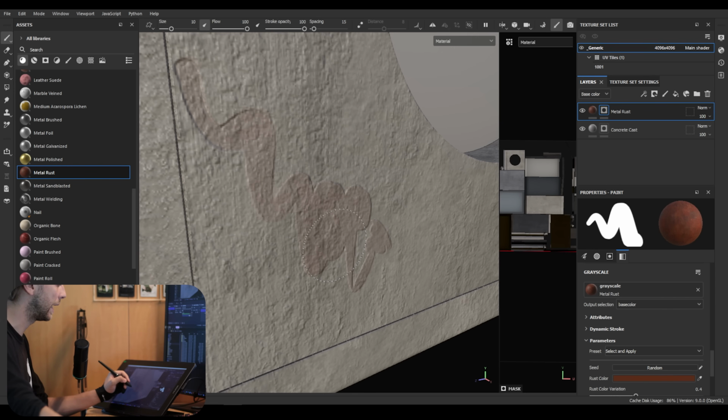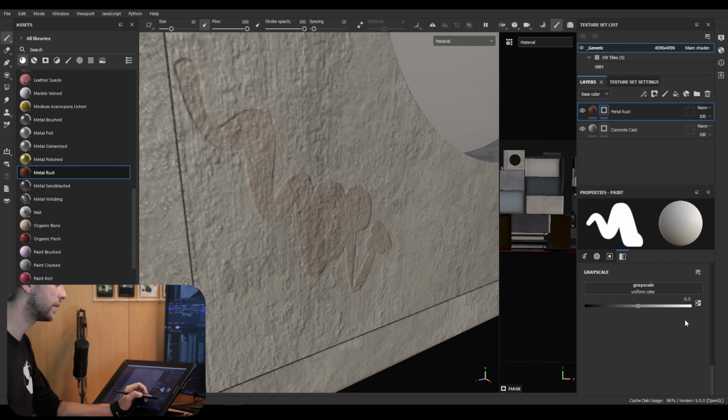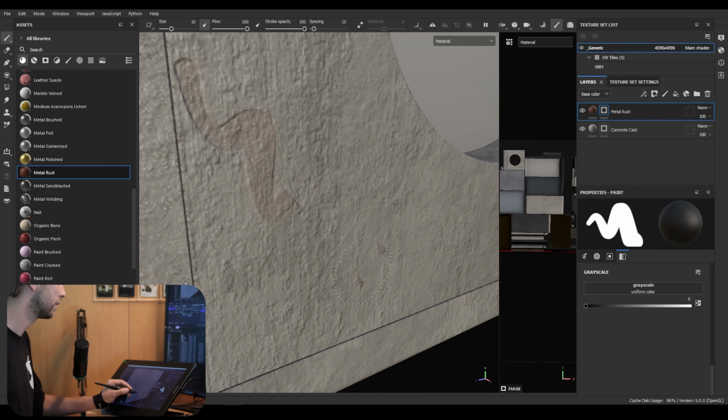The reason why this is bad is because we're using a material rather than a color for the alpha channel, right? So we can't have that. So where it says grayscale, let's get rid of the material. So click that X, and now you're going to be dealing with color. And again, black color means erase, and white color will mean draw.